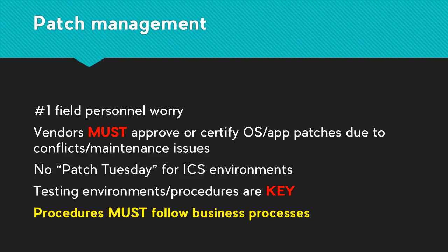Like I said before, vendors must certify or approve these OS level patches and configurations because of compatibility, conflicts, maintenance issues, things like that. So just because Microsoft says this patch is safe doesn't mean Siemens is going to agree with them. Again, there's no scheduled Patch Tuesday for ICS environments. I'm not aware of any vendor that has a monthly patch cycle for their ICS software. I could be wrong, I just haven't seen it yet.